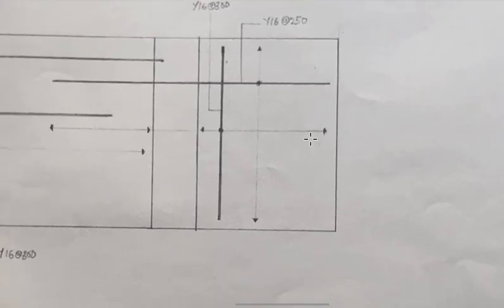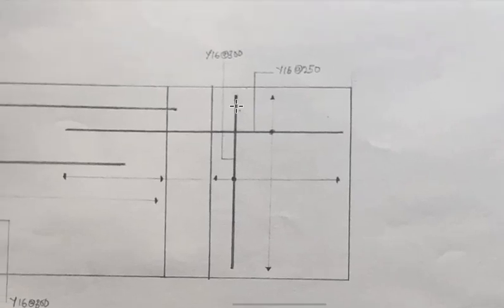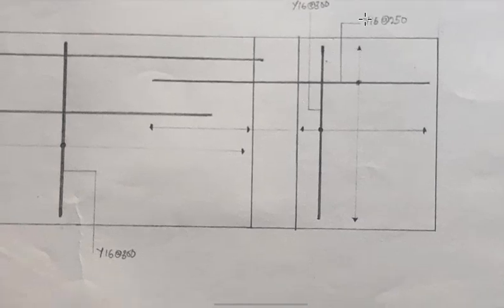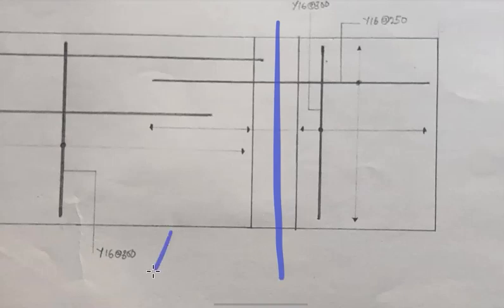What was explained earlier also, that we have our cantilever, meaning the overhanging slab span, which is 2.7 meters. We are going to take half of the area, meaning that our complete area, we are going to curtail it, we are going to stop it at the center of the cantilever slab, then extend half of it by increasing the spacing. But remember, that spacing should not exceed 300 mm. So by reducing the area of bar, we are increasing the spacing.